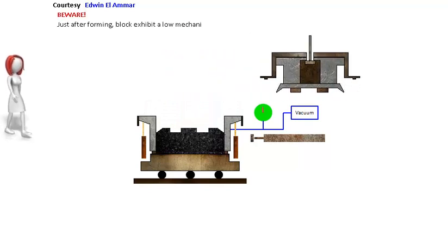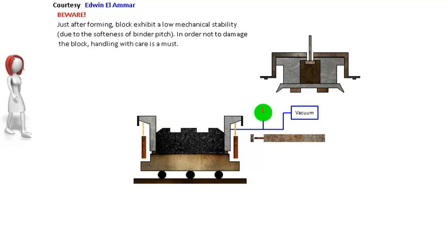Beware! Just after forming, block exhibits a low mechanical stability due to the softness of binder pitch. In order not to damage the block, handling with care is a must. So, to release block from mold, pusher should be run gently. Finish. Prepare to form next block.